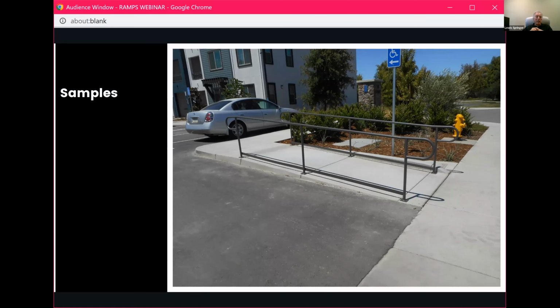So what a curb ramp is not. A curb ramp does not connect a sidewalk to another sidewalk. A curb ramp only connects the vehicular way with the pedestrian way. So in this case, they actually had a series of 3 curb ramps going up because it was adjacent to the curb. They wanted to have it so it was a curb, and we redesigned it so that we had a ramp portion coming up to a level sidewalk.